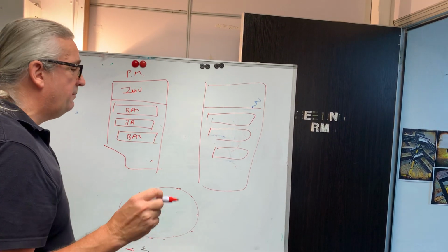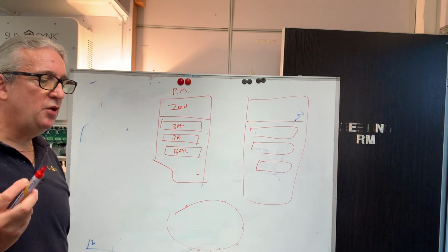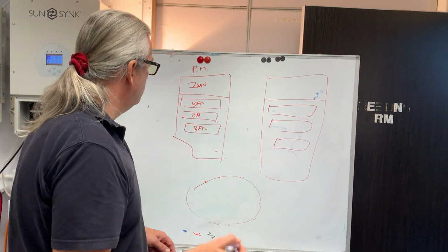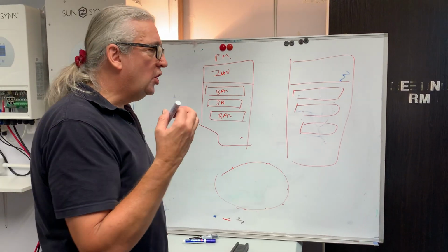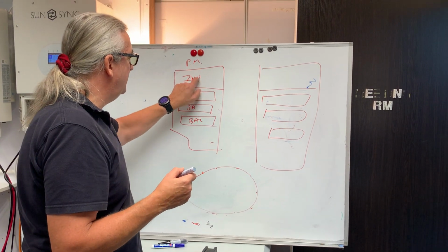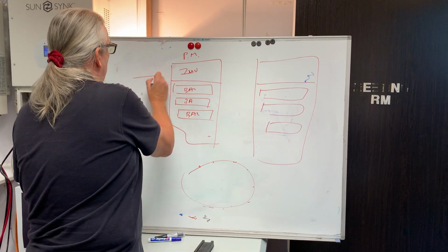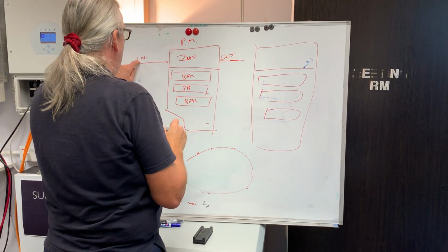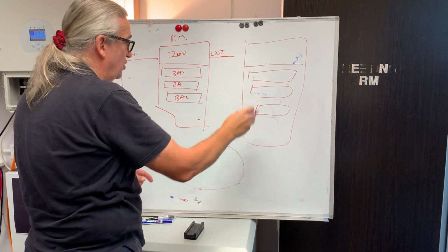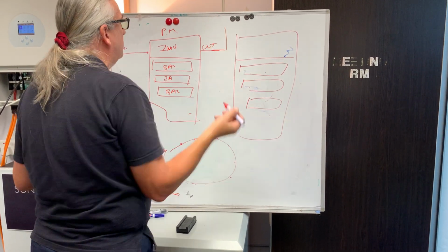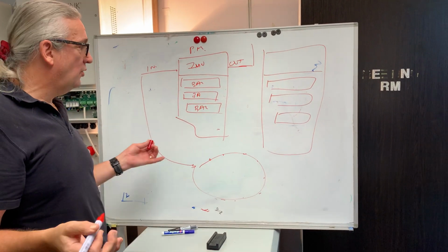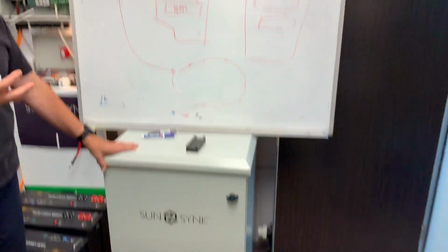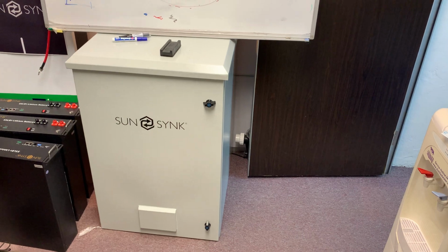Okay. The nice thing about it is when you're feeding them off a cable, you get what they call voltage drops, and especially on big sites, you're going to get huge voltage drops. This can handle it. You can control how much you charge the batteries. So this thing, the inverter, charges the batteries. So what you've got is an in and an out. And that's it. In comes off your grid or your network or your generator. Out goes to your building or your crane or your house or whatever. These look very inconspicuous. And this is what it is. It's simple. Ignore my drawings.